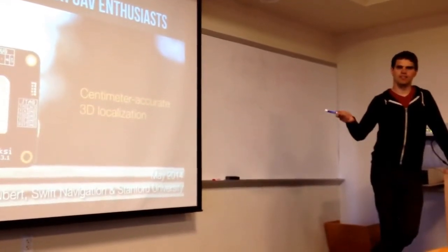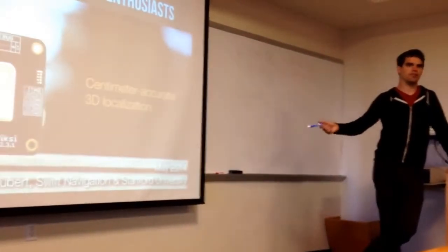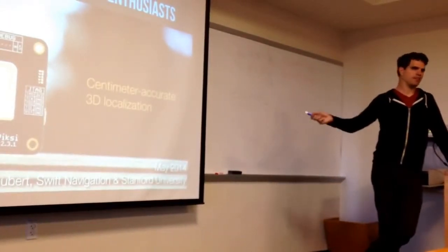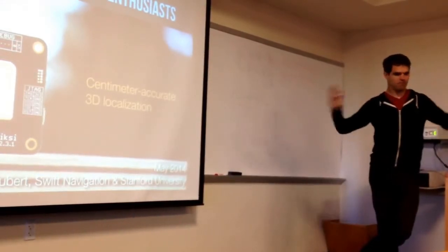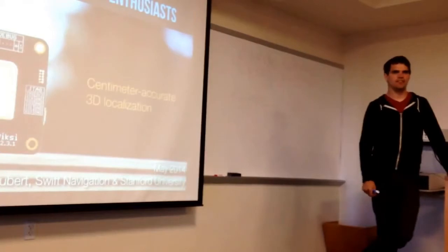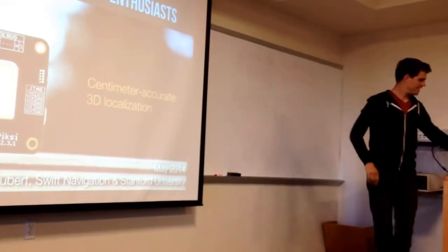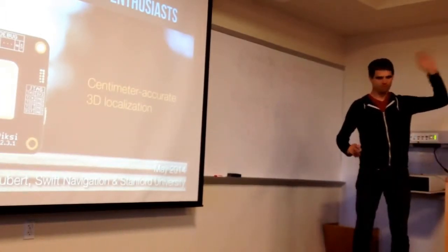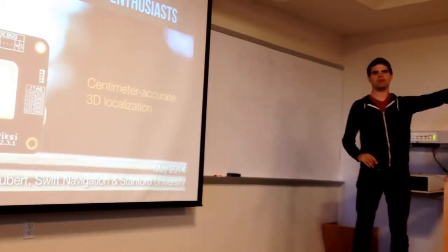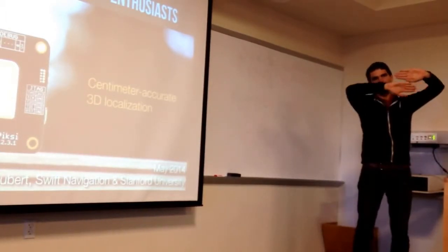Yes, and that's actually part of what's a little challenging, and that's why there's custom hardware on this. The only thing the custom hardware does is you say, here's a set of 20 PRNs, do the search. You've got your incoming signal, and let's say I'm supposed to receive PRN number 1. I take the PRN number 1 signal and then I have to try to align those two.